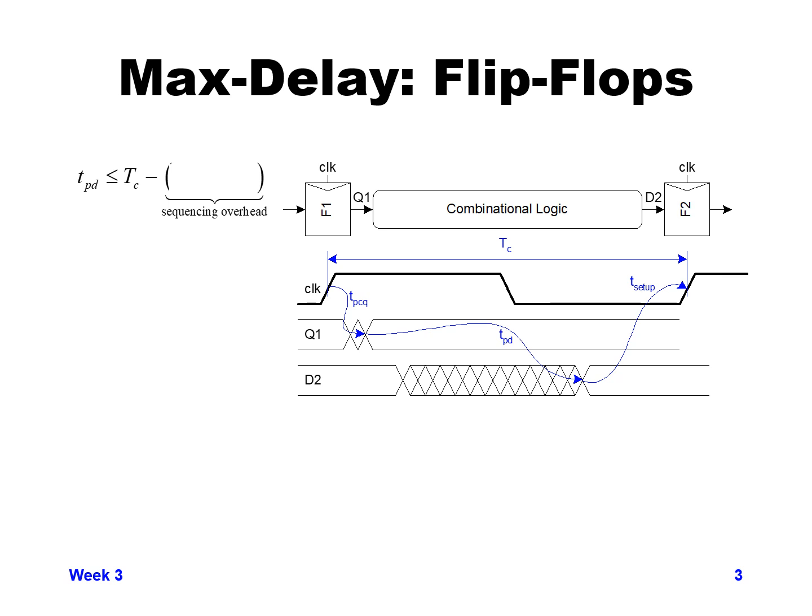So that's shown in the graph below, where you have a certain setup time, and your data has to be there and be stable by that amount of time before the clock switches. You also have a certain propagation delay from the flop on the starting side on the left going into flop 1, and so from the clock rising you have a certain amount of delay from clock rising till Q1 is available.